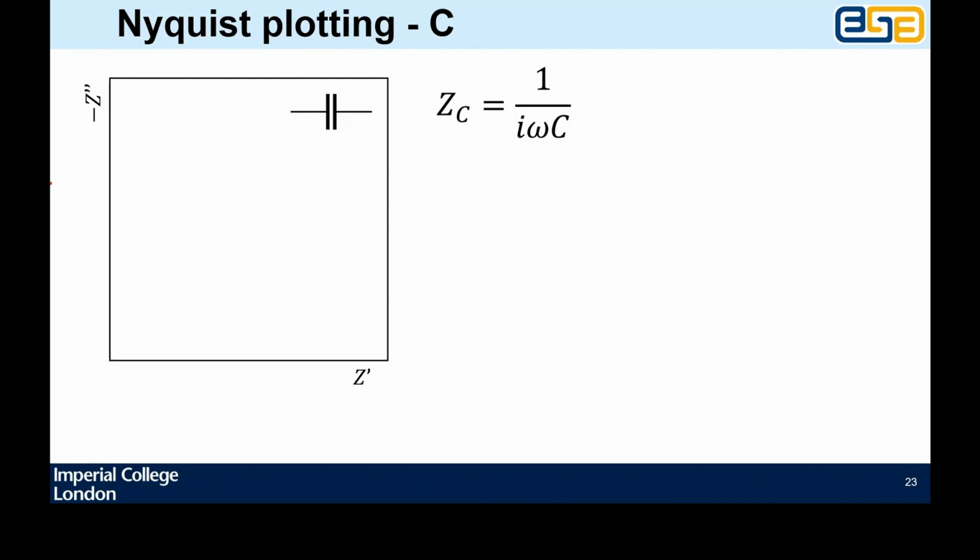What we're going to do in each case is some very crude limits analysis. So we're going to say, what is the limit as omega goes to 0 of Z_C? I put crosses through my z's. Well, as omega goes to 0, that 1 over omega is going to explode off to infinity. I'm going to use slightly sloppy notation here, forgive me, but I think it makes life easier. So this thing equals minus i infinity.